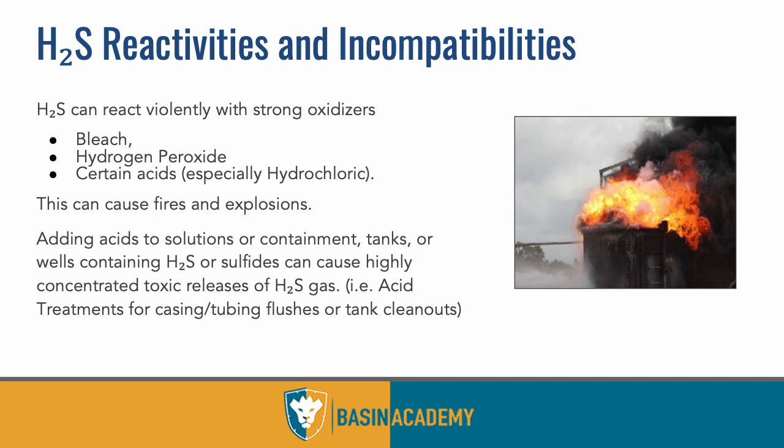So again, that's where we have chlorine and hydrogen. And when you think of saltwater disposal, it's a lot of salt water, right? And salt water and hydrogen mixing together with certain acids is going to bond together and either release H₂S or even potentially form H₂S. So during acid jobs on saltwater disposals, another place you want to be extremely careful. This will cause fires and explosions. It's reactive with metal as well. So as I mentioned, casing, tubing flushes, acid jobs, etc.